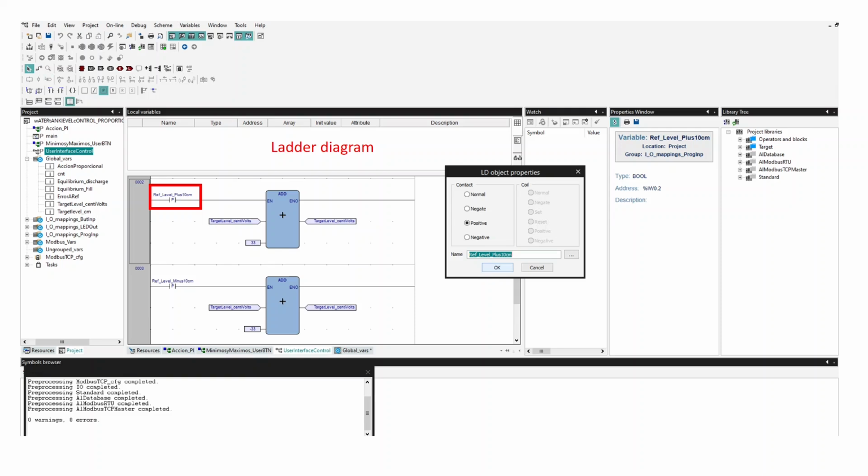Next, we will create a ladder diagram. In this diagram is where we will perform the operation of if the button is pushed, we add 33. In this case, see that the contact that I have squared in red is set to positive. This means that if the contact is detected changing from 0 to 1, then the positive will be enabled, and this action will be performed once.